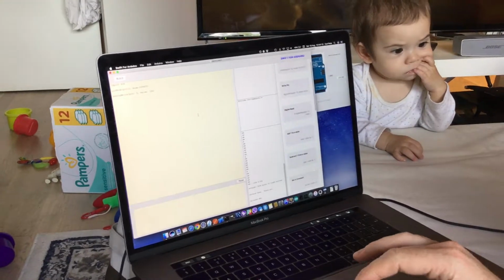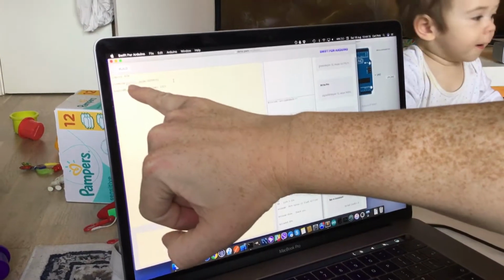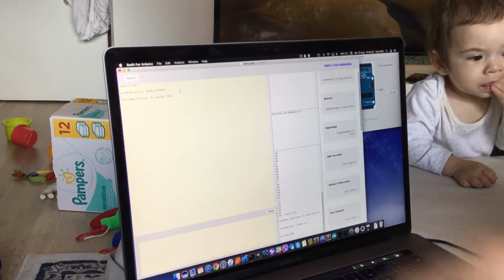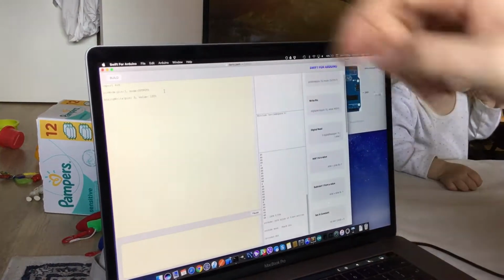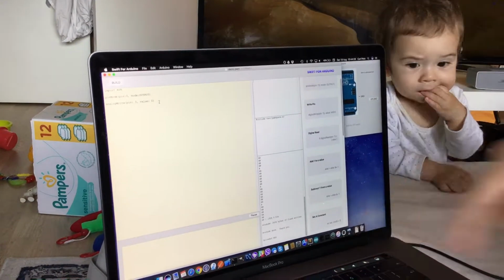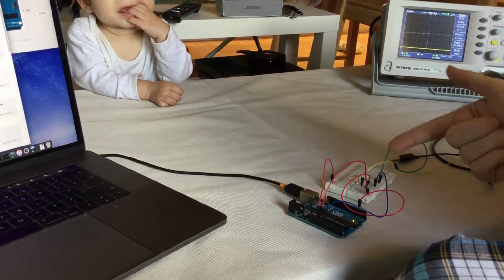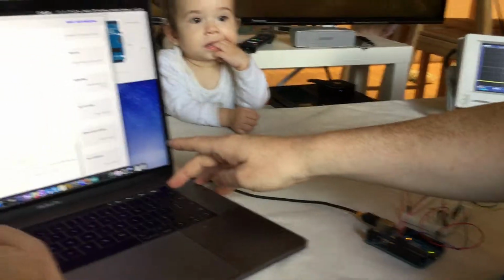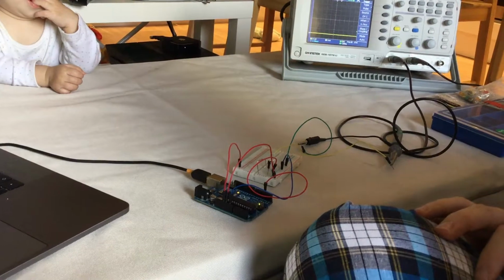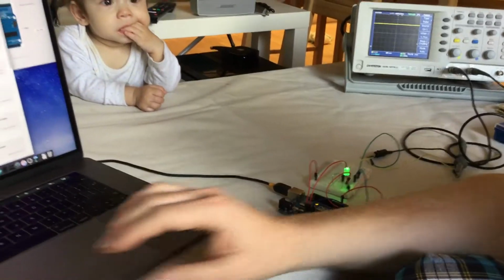And this is one of the key features of the Arduino. If you look at this sketch here, it's really, really simple. We're taking pin 3 and we're saying output, and on pin 3 we're saying value 100. Now this can go between 0 and 255. If I put in 0 and do an upload, if you watch there, it's off. If I put in 255 and upload, it's on full. And these are the values that you'd expect. So this is how an LED works.